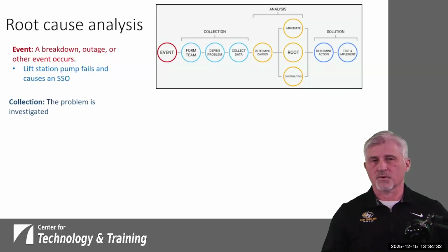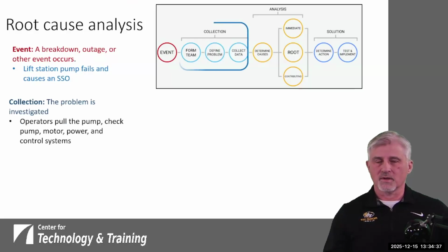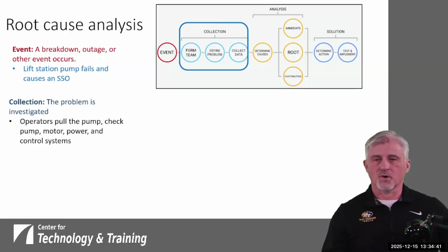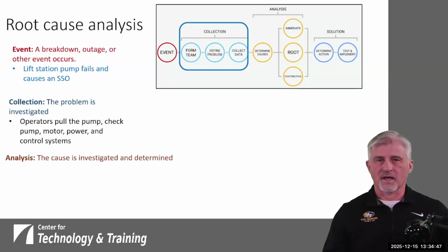So next thing we're going to do, we're going to collect information. We're going to investigate the problem. The operator is going to pull the pump. They're going to check the motor, the pump, the power and control systems. We're going to analyze it. We're going to investigate what was the cause of the failure.